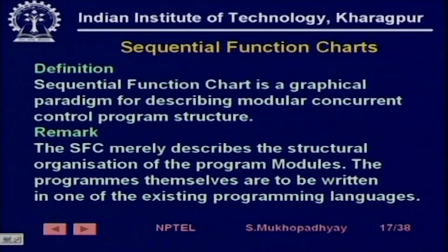So, you have this remark which says that the SFC merely describes the structural organization of the program modules, while the actual program statements in the modules still have to be written, probably using existing PLC programming languages, something like either RLL or instruction list or whatever.